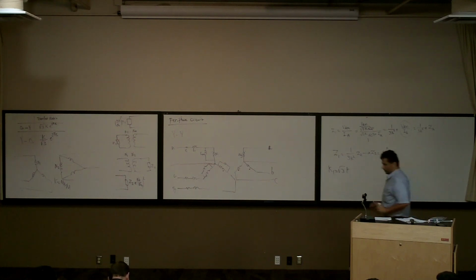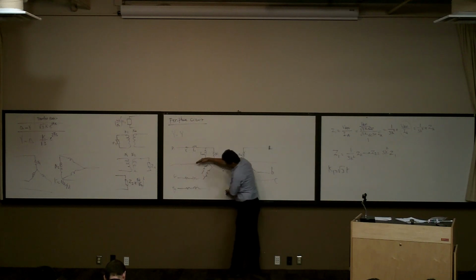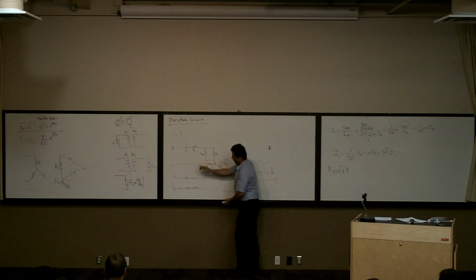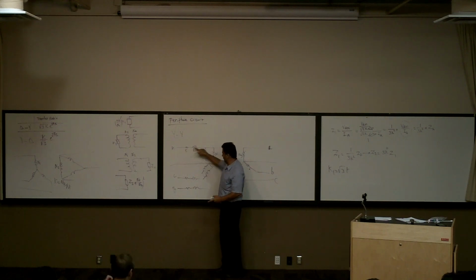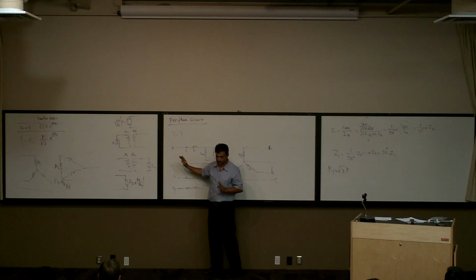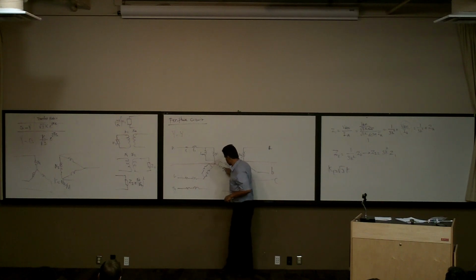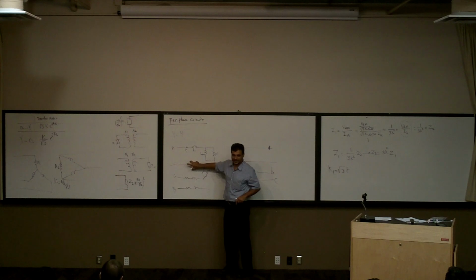Now, see guys, I can break this circuit into three parts. One here, and one here, right? If I have only this part, there is an IA coming here, going this way, right? Think about it. This red wire is going to be common for all three circuits. If I have this circuit, the IC is coming here, going this way. If I have this circuit, it's going to be IB coming here, going this way. So basically, at the end, what current is going through this red wire? IA plus IB plus IC, right? How much is IA plus IB plus IC?